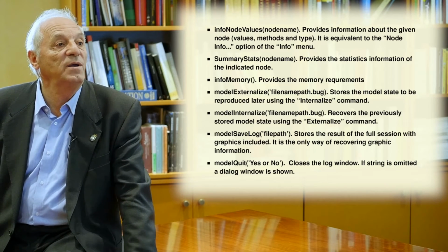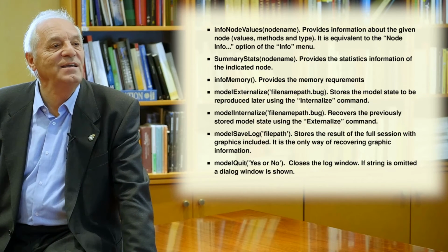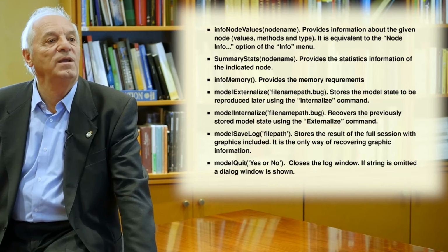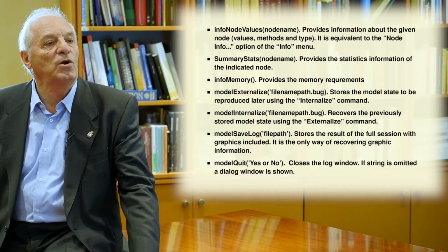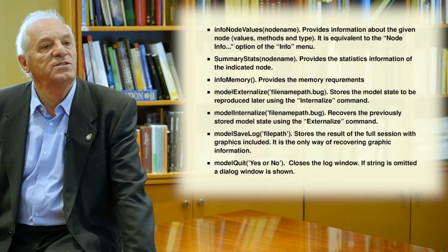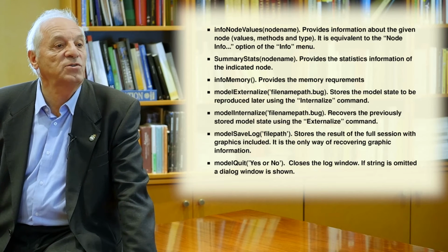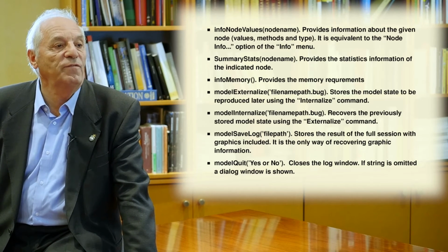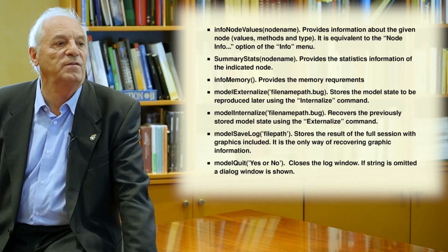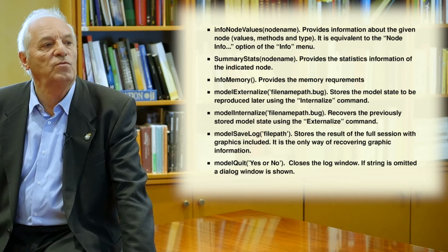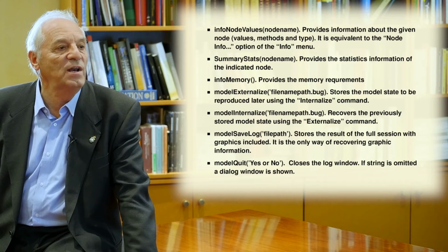We can obtain information about the memory with the info memory command. The model externalize allows you to store the model for being used afterwards, and the model internalize permits you to recover a previously stored model. And the model save log stores the results of the full session with graphics included. It is important to see that this is the only way of recovering graphic information. So please don't forget to use this model save log if you want to use the plots later.